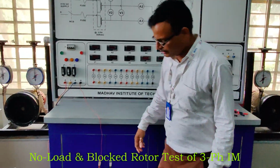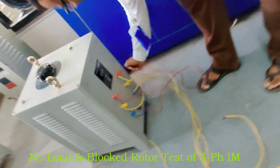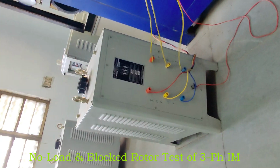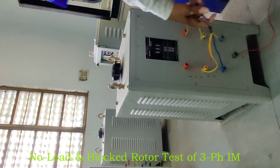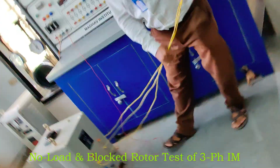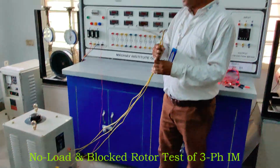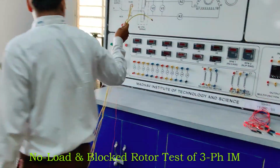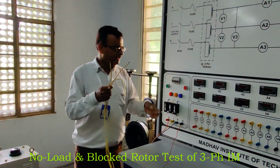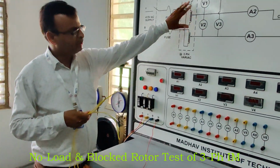So this is the auto transformer, and we will take connecting leads here. This is the input terminals. As you know, the input is the constant 415 volts, and this is the output terminals. Output means variable. The variable outputs will be connected according to this diagram.